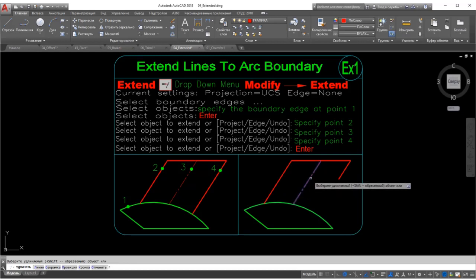You can select multiple objects to trim and extend by typing F and pressing Enter to use the Fence object selection mode, or by entering C to use crossing selection. Even better, you can use implied windowing and drag a selection box to select multiple objects. Step 4. Choose additional objects or press Enter when you are finished trimming or extending.